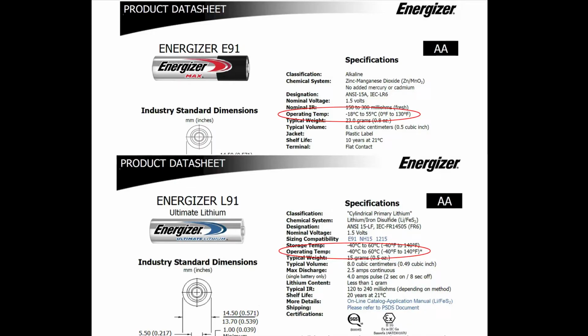He also mentioned that I invest in some lithium batteries to power the payload and not use standard alkaline batteries. The reason for this is that the voltage of alkaline batteries quickly drops off as the battery gets colder. And even though the payload container is insulated, it still gets very cold on the inside. Lithium batteries, because of the chemistry, aren't affected by the cold temperatures as much.